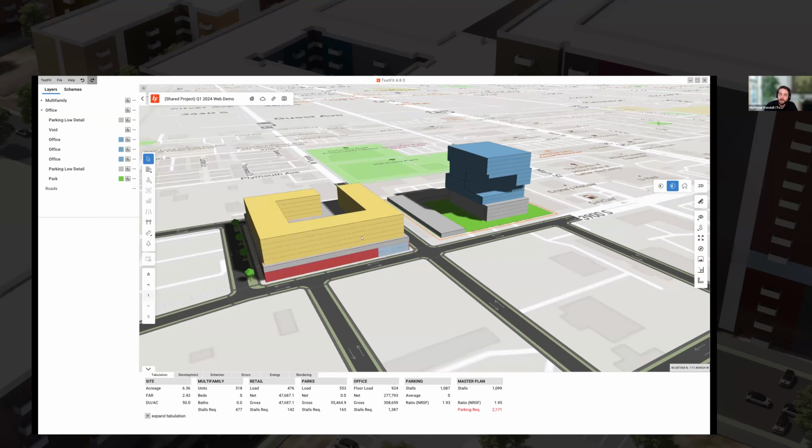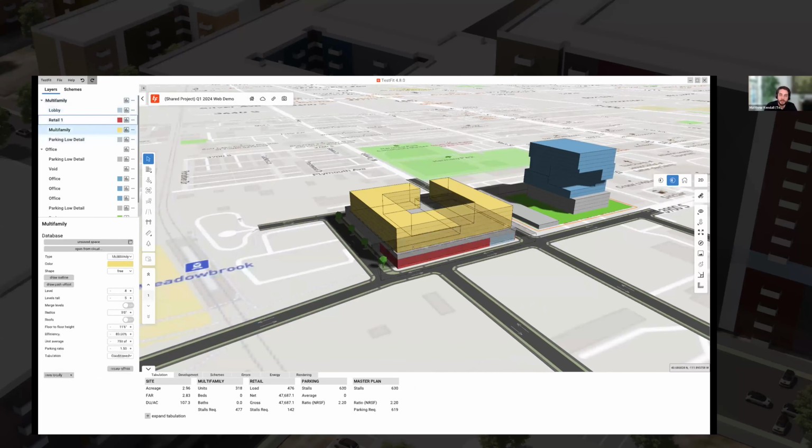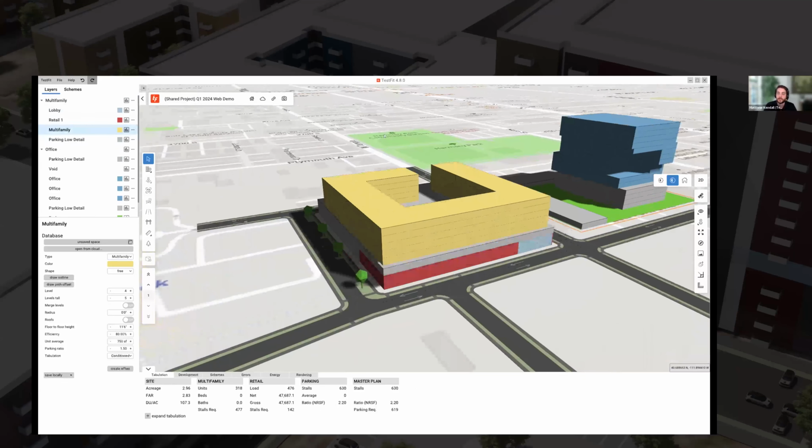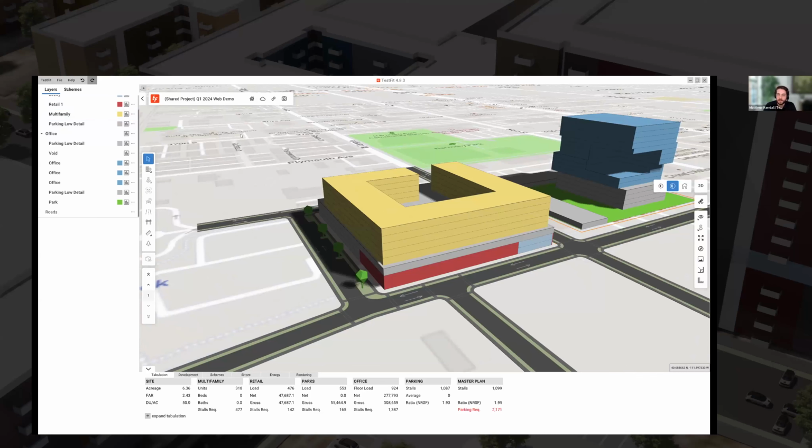What's nice is whenever we have different floors of the same shape, let's say this multifamily area, these 5 floors come into SketchUp as a component itself. So editing one of those floors would edit all of them. You can quickly take this a bit farther inside of SketchUp, using the power of the components themselves to modify these massings and continue working on them as you'd like.